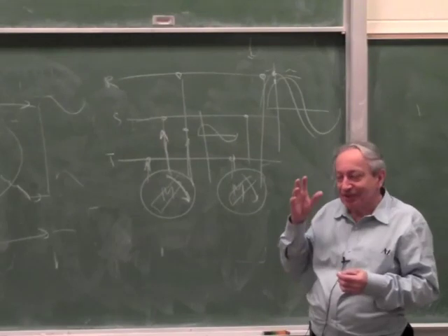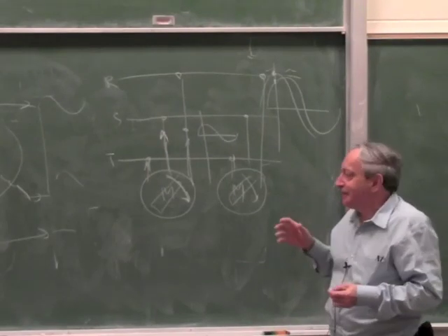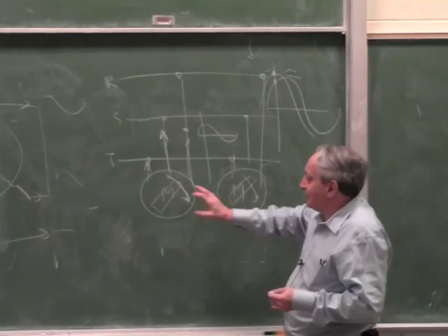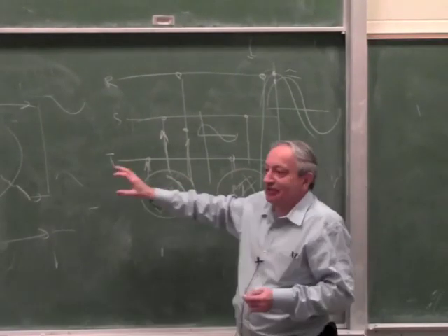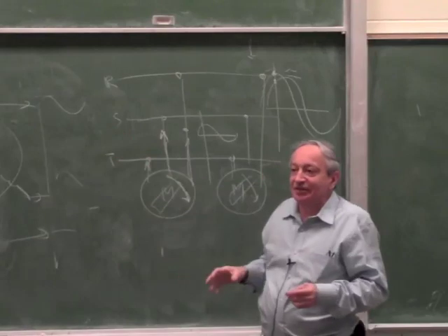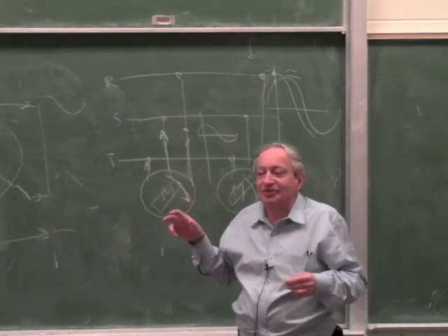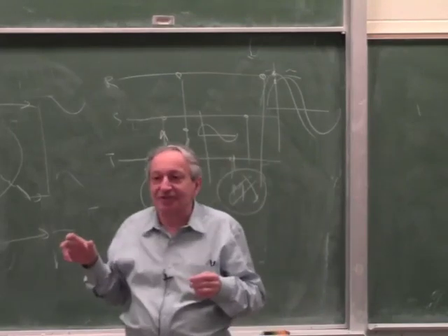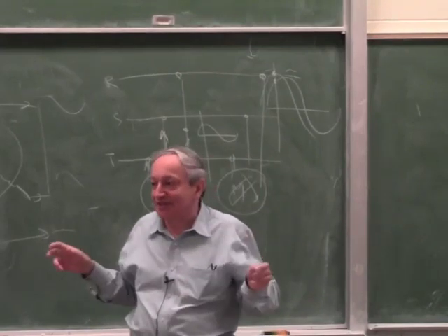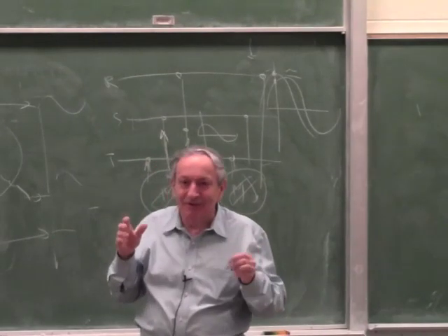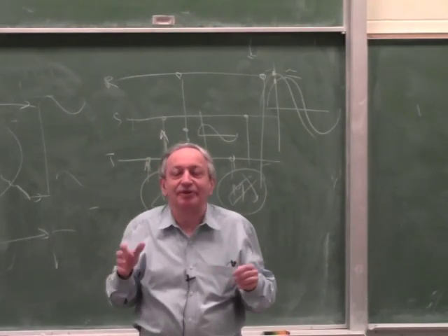So it takes a minute for it to sink in, because then you realize that this works like a mechanical gearbox. Since this is locked to the rotating field, all the motors in the country are locked to the same rotating field. So all the motors in the country which are synchronous behave as if they were geared together. Once you start thinking about it, you realize that that's the only way the grid can work.